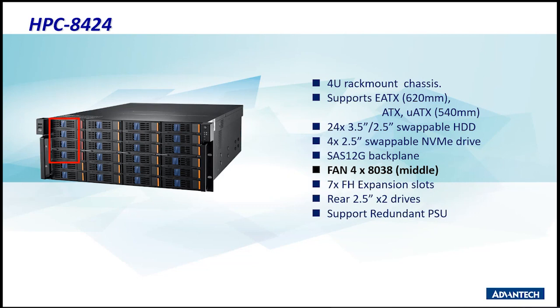Now, to put some numbers on that, typical drives out there in the 3.5-inch form factor are now capable of 10 terabyte. So depending on how much storage you need, as well as the arrangements that are there, in 4U rack space, you've got 240 terabytes worth of storage. So if you're in the video surveillance market, this is something that could be very, very attractive, especially over large geographical installations where you've got high resolution cameras having high frame rates being recorded.